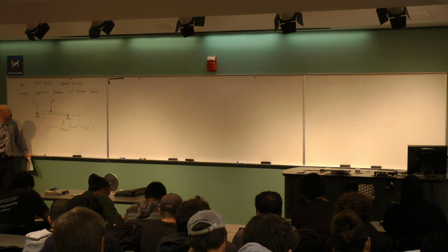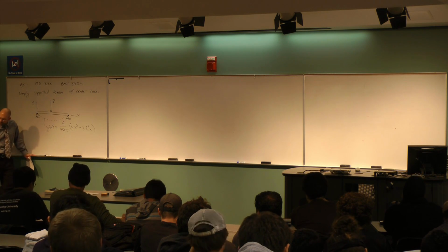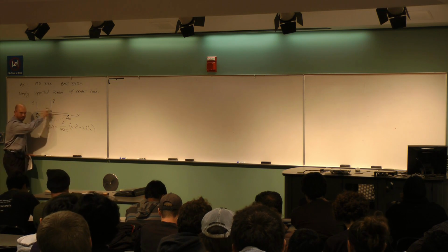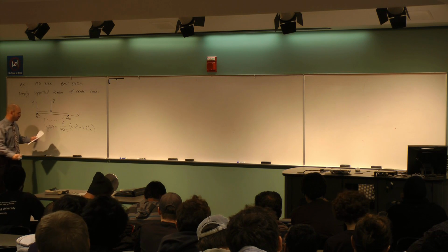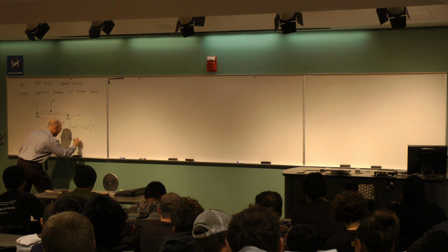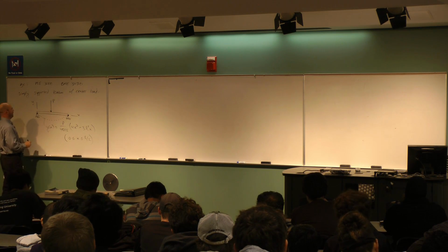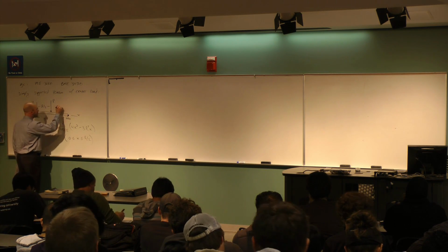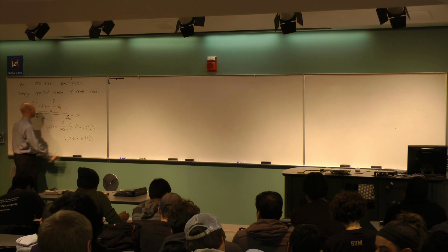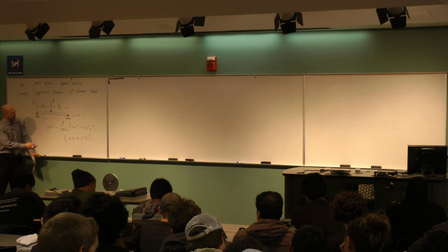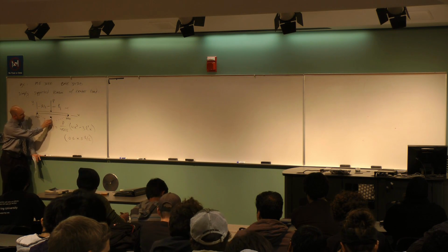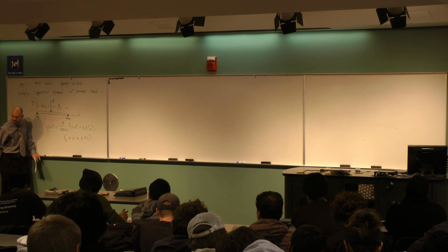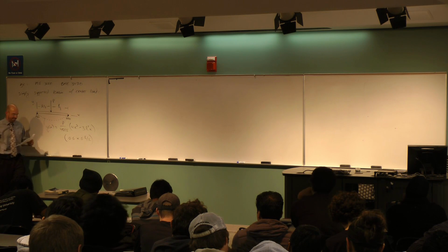And so it turns out that when you have beam problems that have point loads on them, you actually have an equation that's good everywhere in between point loads, right? So it turns out that this is the result for the first half of the beam, 0 less than or equal to x less than or equal to L over 2. And so L over 2 is where the load is located, right? The entire length of this thing is L, and that's why we call it a central load. Since this is going to be symmetric because the load's in the middle, if I have the equation for the left half, then if I want the answer on the other side, I just flip it about the middle. So, that's what we have for the deflection y of x.